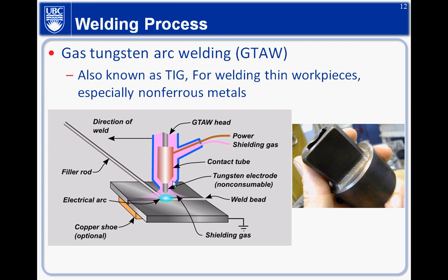Okay. TIG weld, the gas tungsten arc weld. This one basically uses a non-consumable electrode. It's a tungsten. Basically, the electrode here is a tungsten. And there is shielding gas coming from here. Then your filler material, or filler rod, is a separate stick. Basically, you can hold a gun here and hold the filler rod in the other hand, going along this weld here, right?